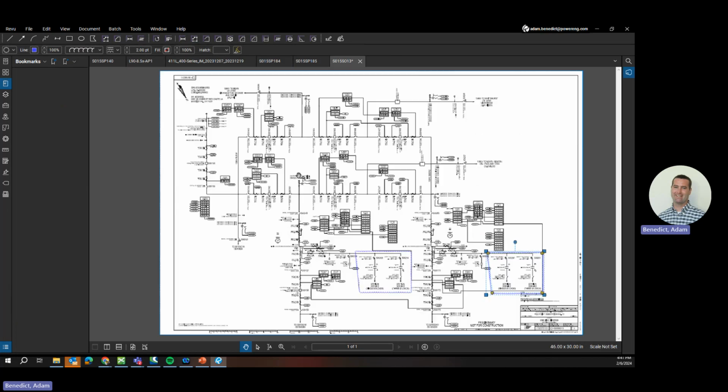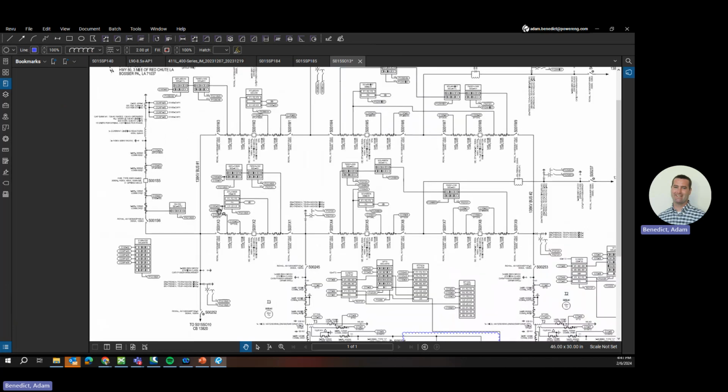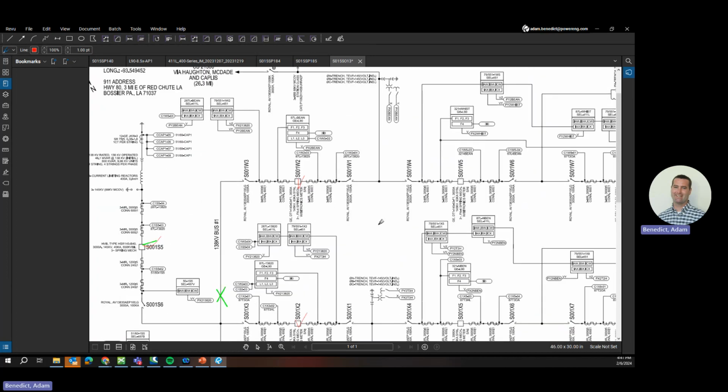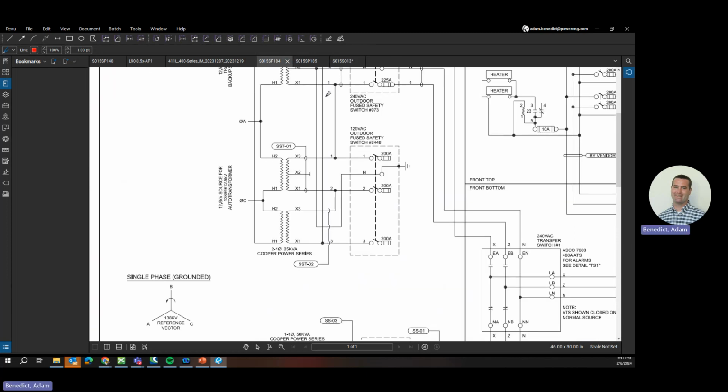And then additionally, we will calculate the overall momentary load. So in this case, I believe it was this node. Here we calculated based on a fault here, we would trip this breaker. So we'd have that trip coil, this trip coil, and this trip coil. These trip coils would be added to the calc. And then occasionally, not this utility, but other utilities would say, okay, well, that trip failed, so we need to include this trip coil as well. So based on the momentary and the constant loads, it would spit out a battery size.